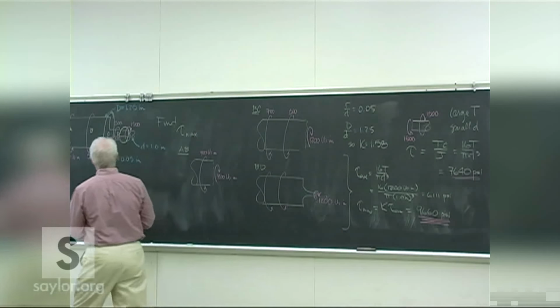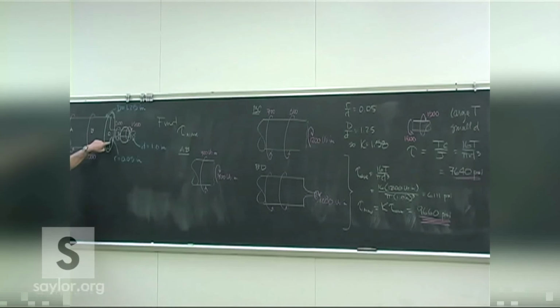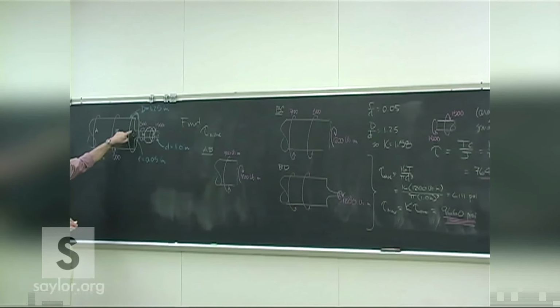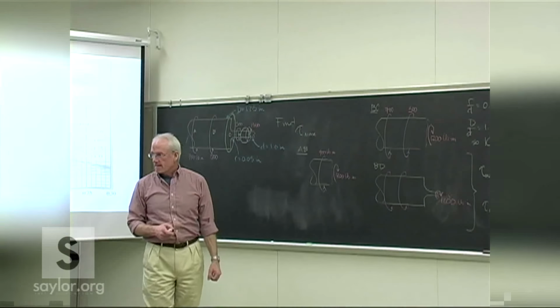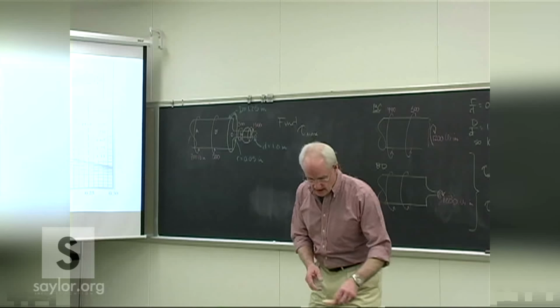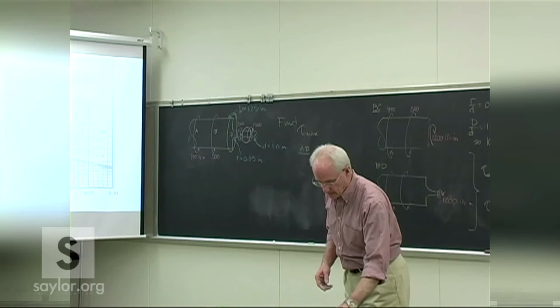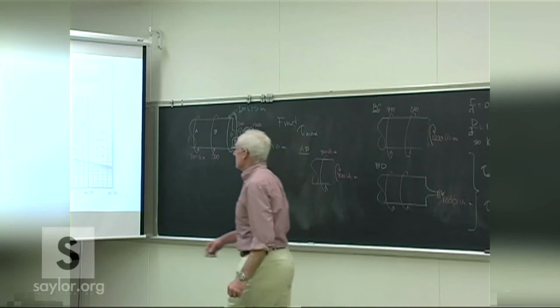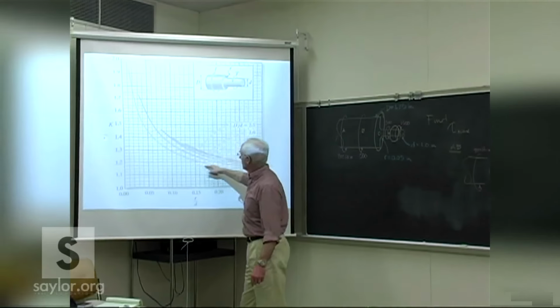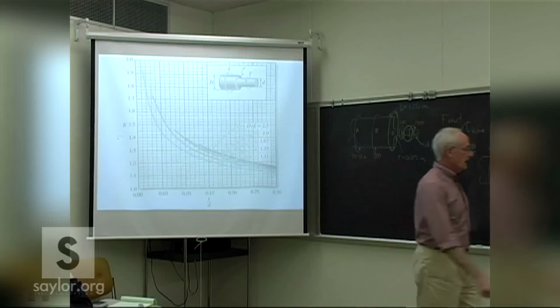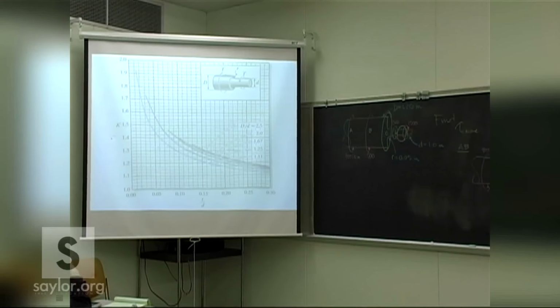So the area of concern is at the step change. You might want to investigate increasing the fillet radius. If it's machined in, that's usually not too difficult a change to make. That would bring you down to a lower K factor, and can significantly drop this number.